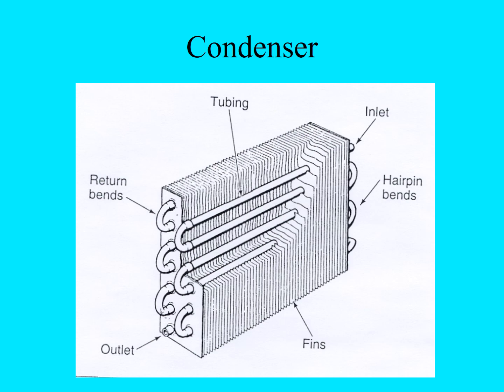So the condenser is where we're going to get the refrigerant, high temperature vapor, to cool off and condense into a liquid. So this is a series design condenser. In other words, the refrigerant has to flow in series right through the tubes, coming in at the top as a vapor, and when it leaves, it's coming out of the bottom as a liquid. And again, there's cooling fins that surround this. The more surface area the condenser has, the greater capacity it has to give up heat.